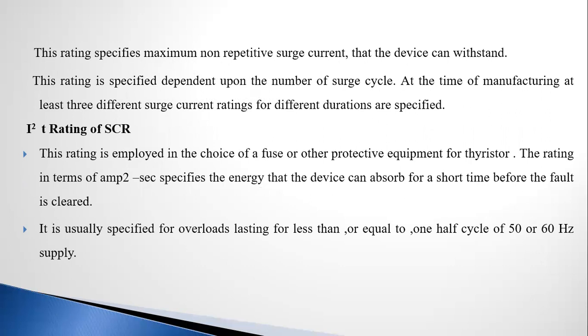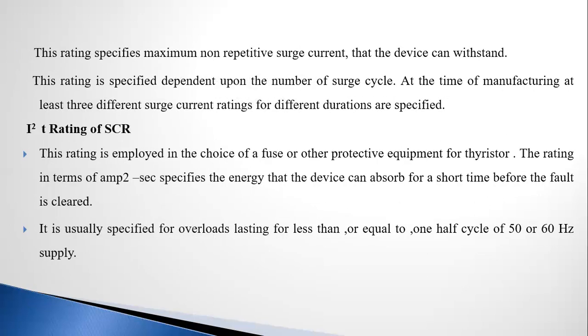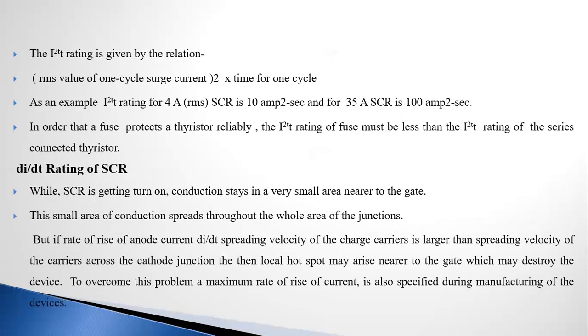Now, next one is the I2T rating of the SCR. This rating is employed in the choice of the fuse or other protective equipment for the thyristor. It is usually specified for an overload lasting less than or equal to 1/2 cycle of a 50 or 60 Hz supply.